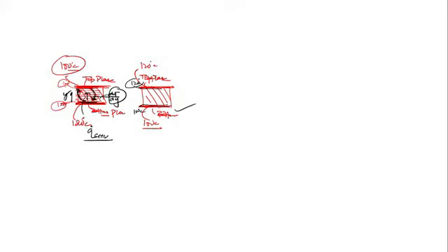Upper. Then will there be any convection current? I think here the fluid layer will not displace. Why? Because heavier density fluid is already at the bottom and the lighter fluid is already at the top. There is no convection current. No current will develop. No bulk motion is there. Only molecular motion is there, but there is no bulk motion.